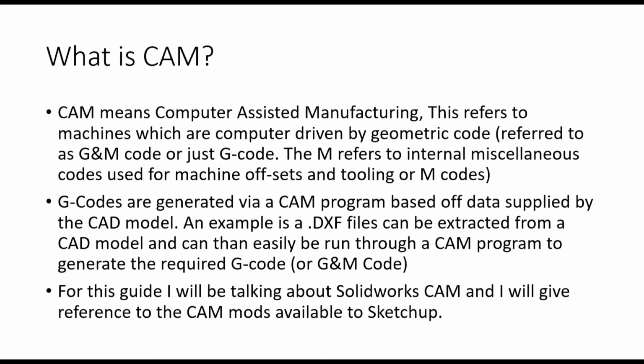You did mention the other day, and this is a general note for anyone out there, that nesting, or running a nest, is just putting a whole bunch of parts, or a whole bunch of DXFs, into a single bigger DXF. You can manually create your nestings if you wanted to. I can create an assembly in SolidWorks, lay out all the parts within a 1200 by 2.4 area, or whatever the material size is, and then export that into a DXF and create my own nest.